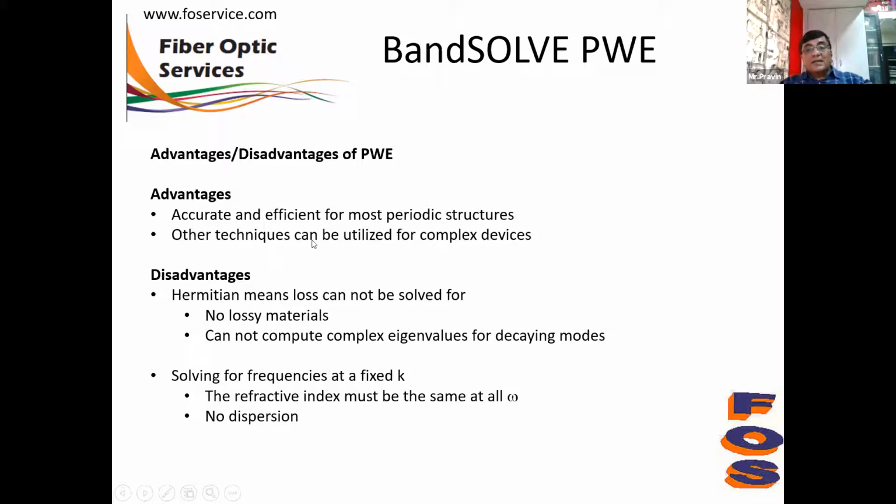The other technique can also be utilized for complex devices. The disadvantage here is it cannot include lossy material, and it cannot compute the complex eigenwave value for the decaying mode. Also, the refractive index must be the same for all frequencies. So no dispersion.